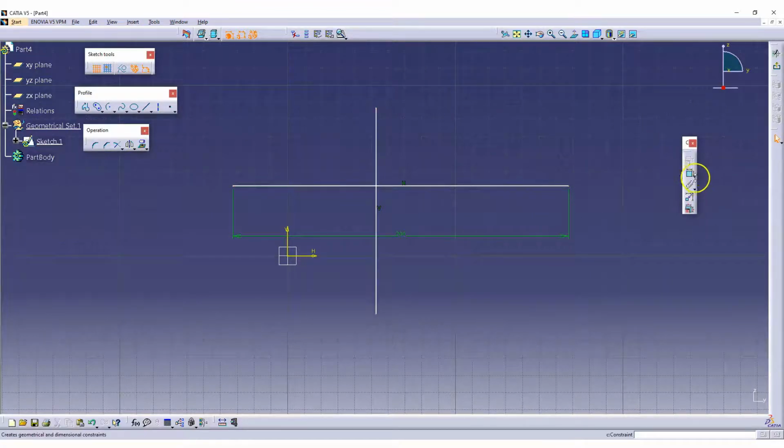So what I do, go there, from here to here you can make it a dimension, or else what I'm going to do is break the entire line using this particular line. So that means this becomes one entity, this becomes one entity. Now you just select this one, you get this dimension, right? So you can use this breaking line to break any lines, whether it is a line or plane. Even with the plane also you can break it.